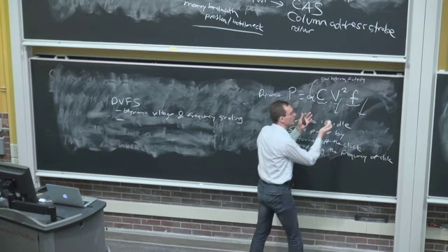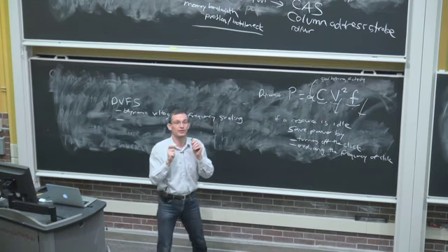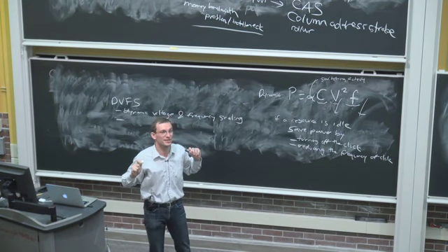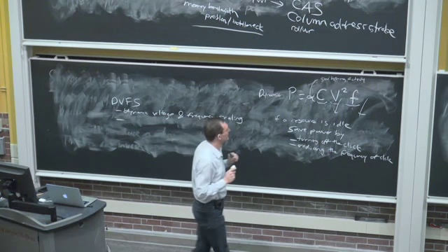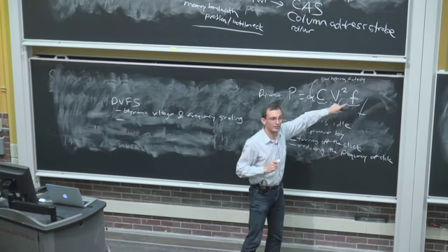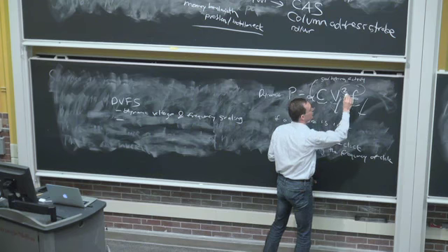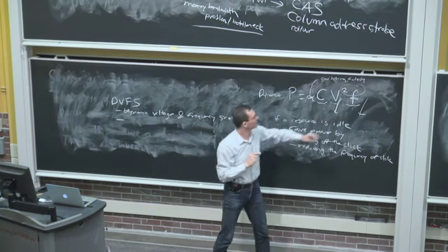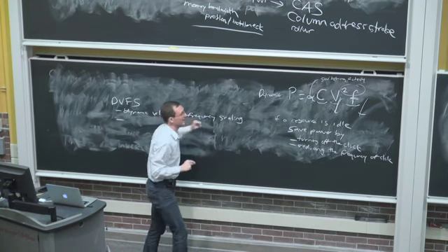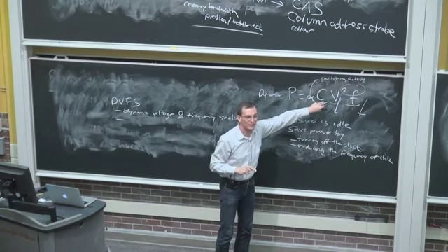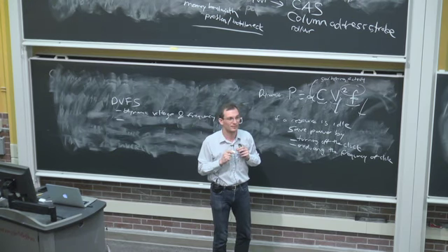So if you're not using a part of the core, for example, let's say your core is waiting for a memory request, very long latency memory request, an I/O request. That's going to take, I don't know, 1,000, 2,000 cycles. Why don't you scale down the frequency of the core? And at the same time, why don't you scale down the voltage of the core? Now your power goes down in a cubic manner, right? And that's the idea of dynamic voltage and frequency scaling, to reduce the power when you don't need the performance from the core. Does that make sense?